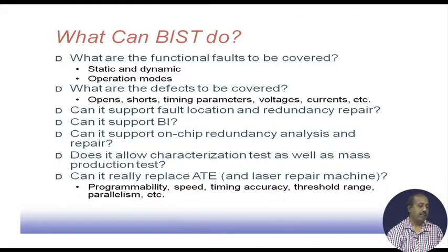Does it allow characterization test as well as mass production test? Characterization test can check the memory thoroughly, while mass production tests do not do a thorough check, but are much faster, though all faults may not be covered. So, does it allow both of them? Can it really replace ATE and the laser repair machine?